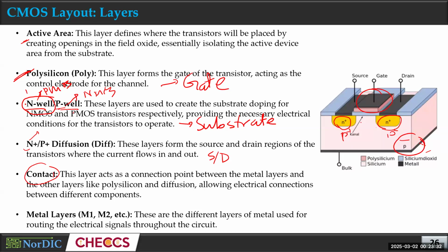For the transistor, we need to separate the source, gate, drain, and bulk, right? These four terminals, because when you build the inverter, the gates were connected, the source was connected to something, the drains were connected, right? If you make complex circuitry like NAND, NOR, you will have much more complex connections.